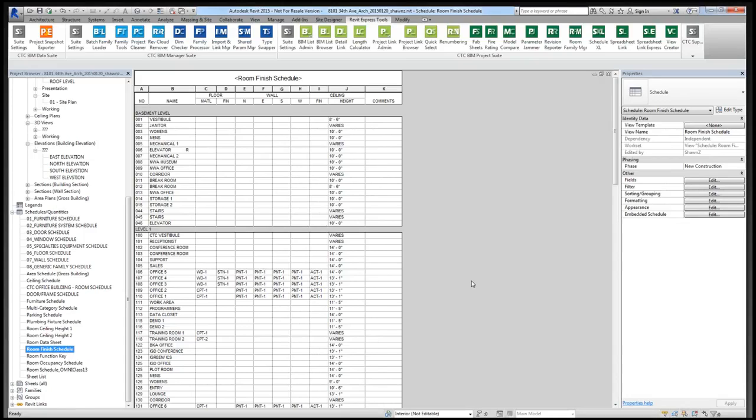And so another individual said that in their Revit model, the volume of the room is not controlled by the ceiling object. So the ceiling itself has the room boundary on, but the limit offset basically is what's calculating the height of the room, and that's fine. If you've got a top limit offset on that room, and you're carefully controlling that, you can use that directly in Revit. You don't even need to run extra math if you're actually leveraging it.